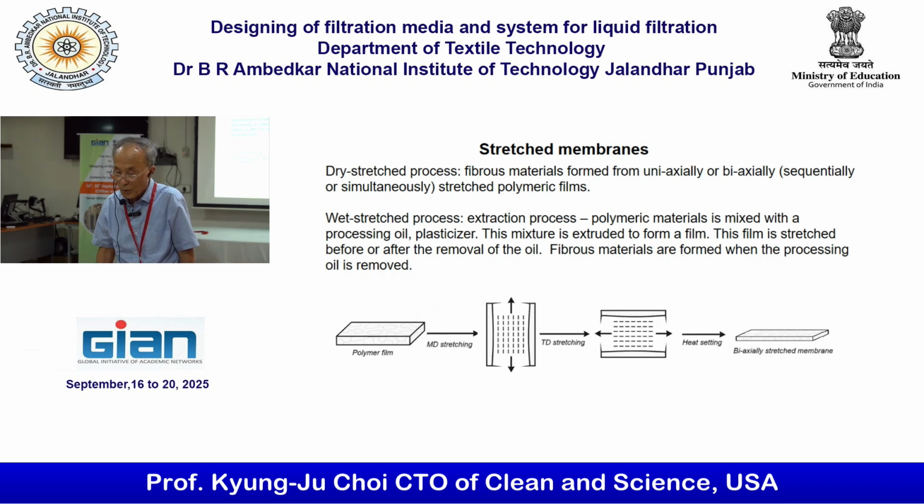The trouble is, if we get some raw material, PTFE material from, let's say, China, then during the shipping the temperature is going to go up more than 19 degrees, and then you have a problem. So they have to put it in some cold box. Also, they have to control the temperature inside too. So 19 degrees is critical. They have to maintain less than 19 degrees.